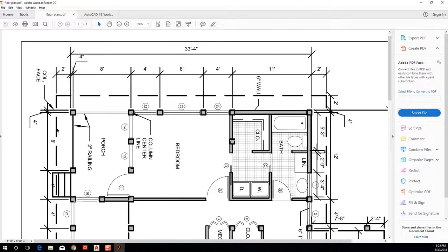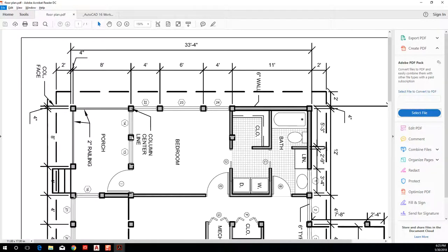So when I look at these drawings, the outlines of architectural elements like columns and walls have the heaviest pen weight. They're very thick black lines, okay? Secondary architectural elements like the windows and the doors have a thinner line weight than the columns and the walls.